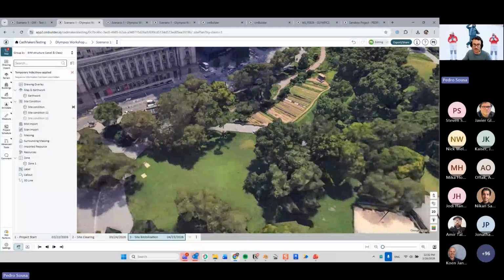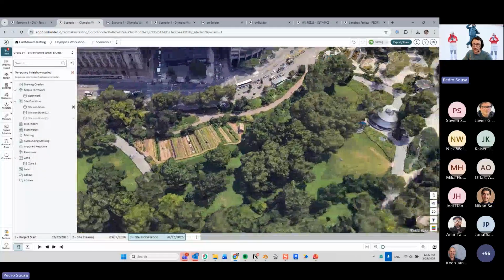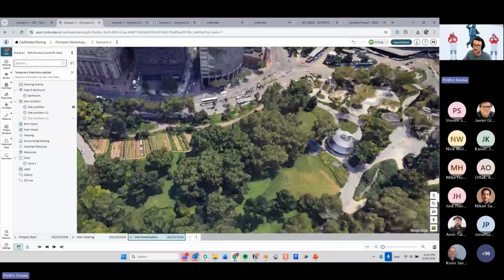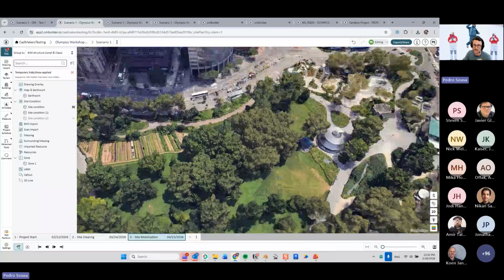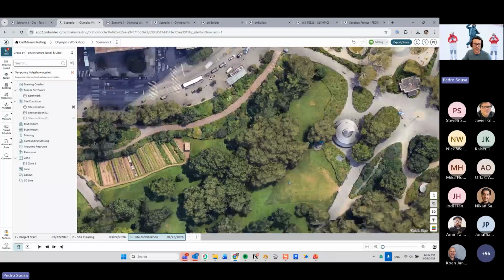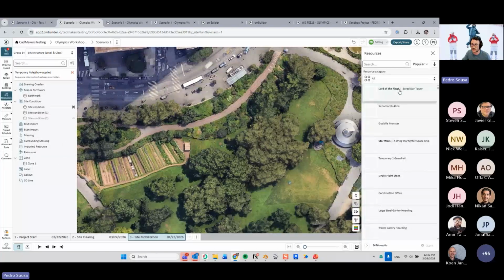For the lack of a better way to explain it, always consider that everything that is created by default from the Google Maps is terrain. So things that refer to the terrain, like project on terrain and things like that, will also take into consideration the shape of the 3D models here.